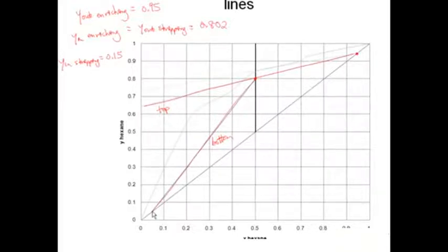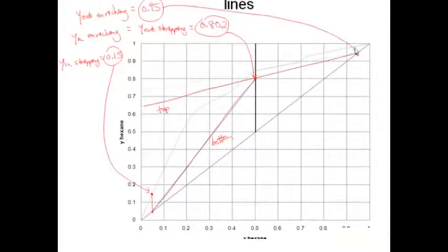Because for a partial reboiler we have x out which is xb, is in equilibrium with the vapor coming off of the partial reboiler. So we go up here to get 0.15, and then the 0.802 was right here, and the 0.95 was right here.